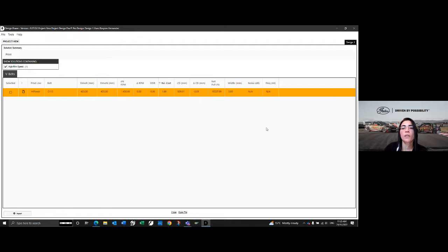For this particular one, the program will give you only one solution, in a color, which gives you a warning if you see here: a high ring speed. Because this is an existing drive, you can see that the drive has a problem. So the customer probably has to change to a better drive. That's why they have some issue.